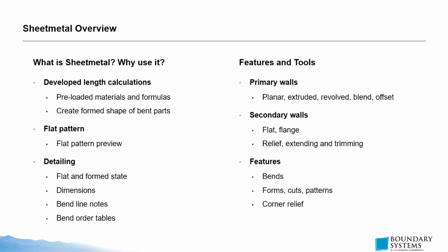If any of you have used sheet metal in the real world, you may have noticed that the dimensions you start with and your final dimensions are not going to be the exact same. The reason for that is that every bend is not going to be perfect. You're not going to have a perfect 60-degree angle that preserves all of the material in exactly the same way. Any of these bends are going to be done along a radius, and that material is going to be stretched, and it's going to deform in very predictable ways.